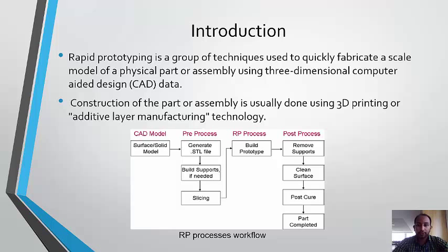The flowchart below shows the workflow in the rapid prototyping process. First, the process starts with 3D modeling of the product, which is then converted to STL format. The resolution can be set to minimize stair stepping. The rapid prototyping machine processes the STL file by creating sliced layers of the model. The first layer of the physical model is created.